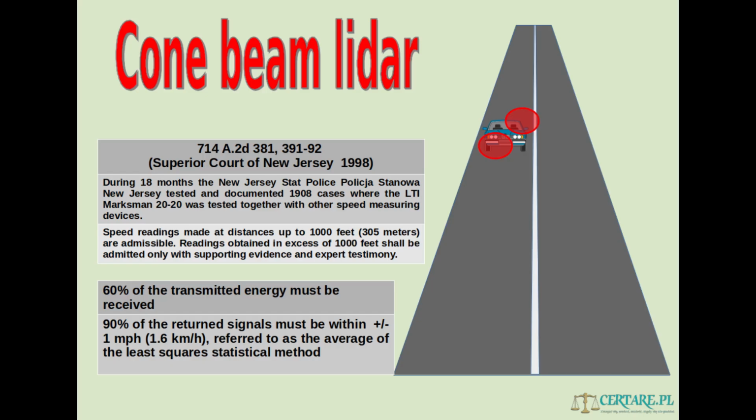But there are situations which I was able to document where that algorithm is not able to detect an obviously erroneous measurement, where the operator starts measuring by pointing the lidar at a grassy hill near the road, then slides it along the road and ends up on the motorcycle, and the lidar does not detect this as an erroneous reading. That's the kind of problems I'm talking about.